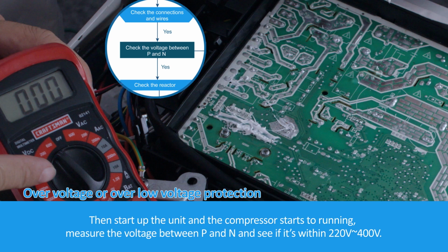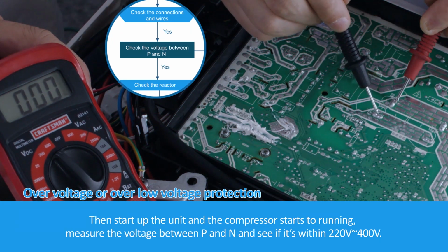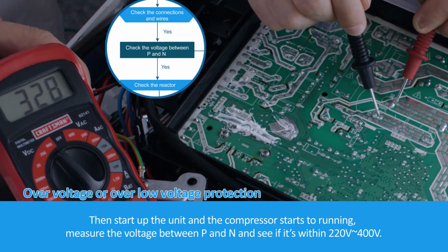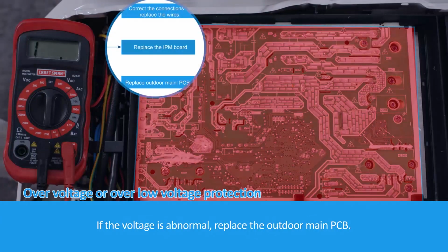Then start up the unit and let the compressor start running. Measure the voltage between P and N and see if it is within 220 volts to 400 volts. If the voltage is abnormal, replace the outdoor main PCB.